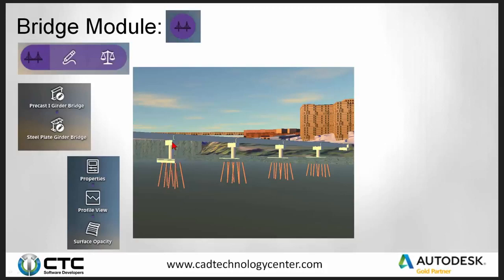With the bridge module, I have the ability to adjust where the location of these are at. Maybe I need a 70-foot span between two of them because I'm putting a road underneath. But on the outsides, I can get away with just a 40-foot span. So maybe I have to beef up my girders in the middle because it's covering a 70-foot span, whereas when I'm doing a 35-foot span or 50-foot span, they don't have to be as much. And as I widen those columns, it will know, hey, you're at 70 feet, and it will increase the size of your girders to match.